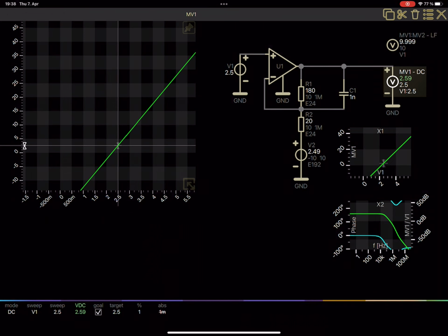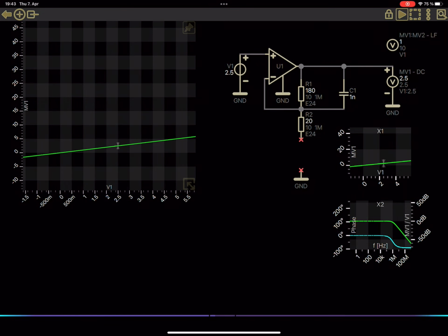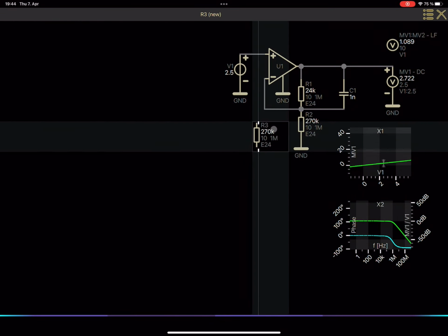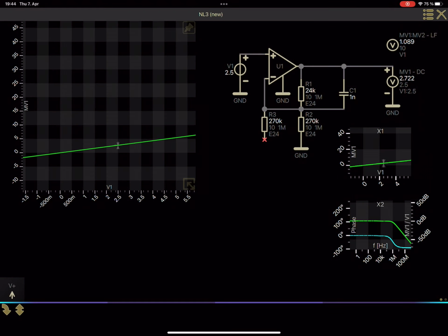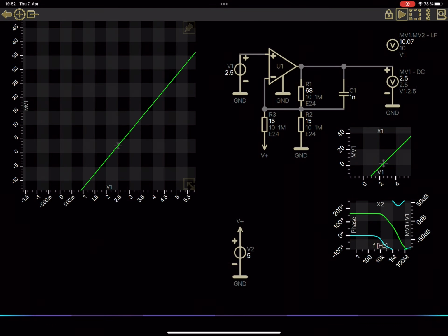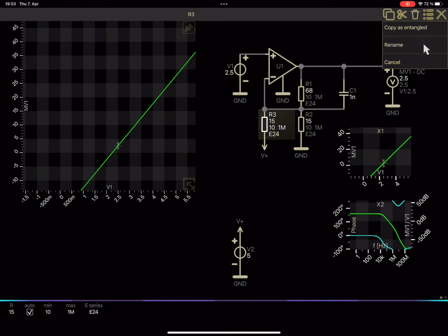We get rid of the virtual reference voltage V2 by utilizing Thevenin's theorem to substitute V2 and R2 with a voltage divider. If needed, for example for bias current compensation, the inner resistance of this network can be well defined with a little entangled helper circuit.